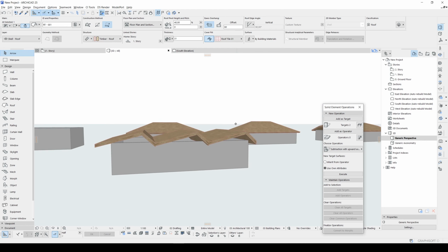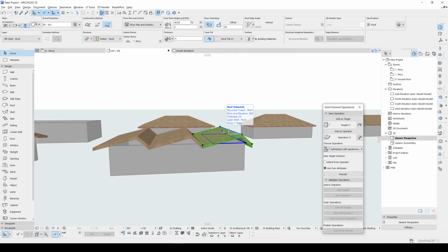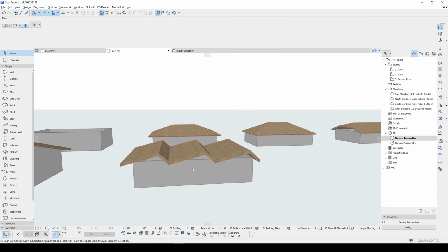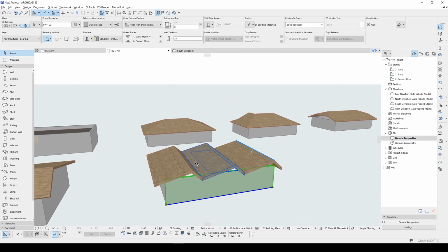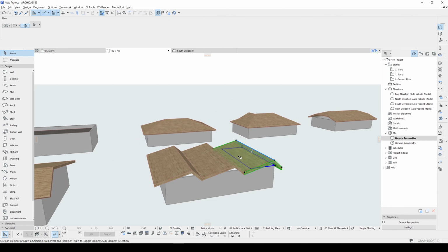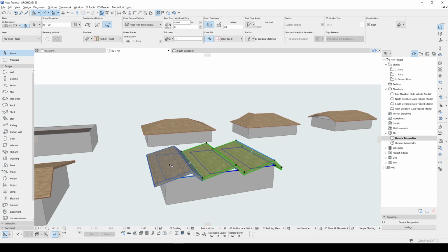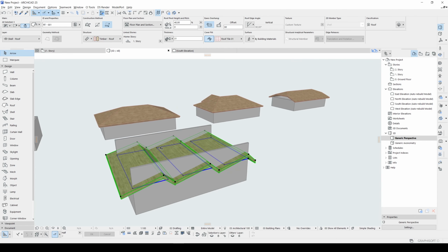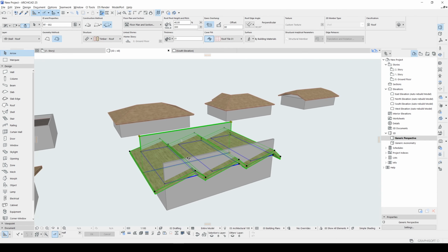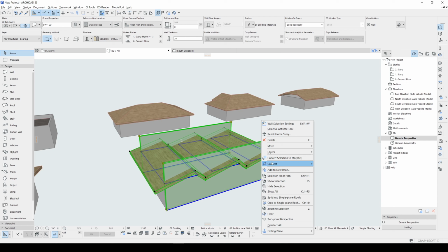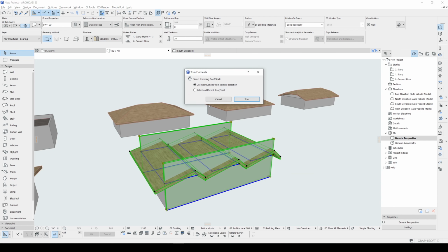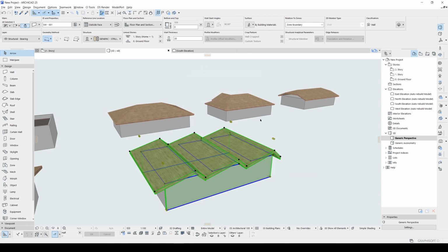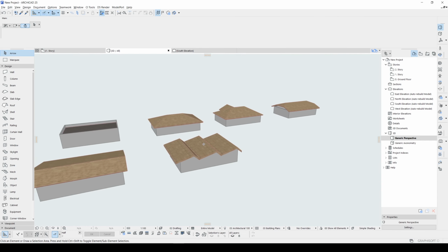And here once more. After that, we are going to trim side walls from the roofs. Let's select all of the roofs and our side walls. Connect trim elements roof shell and use roof shell from trim. Yeah, that's all.